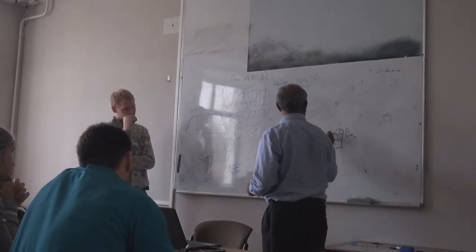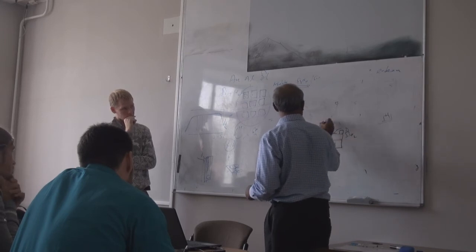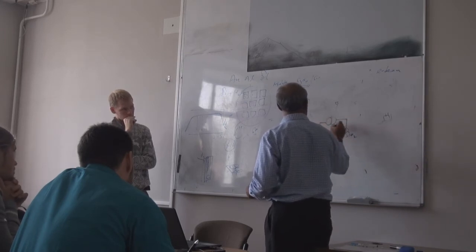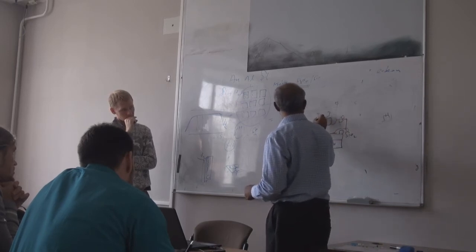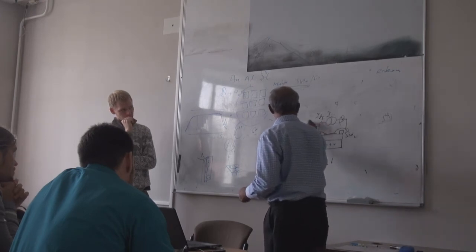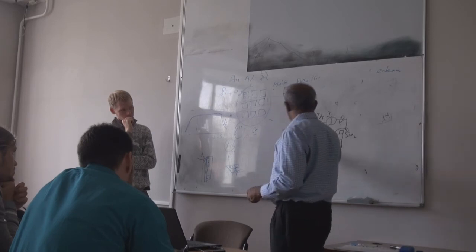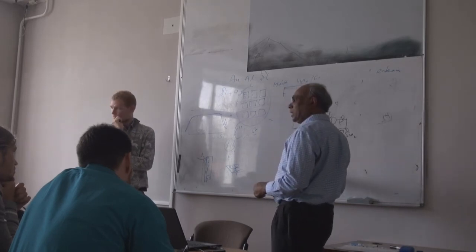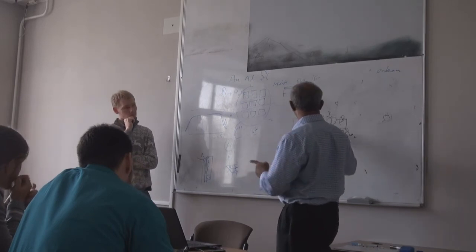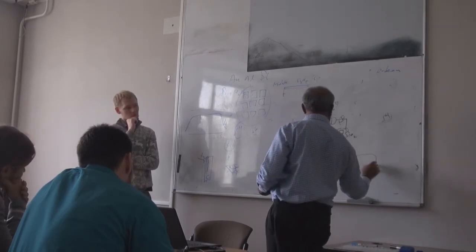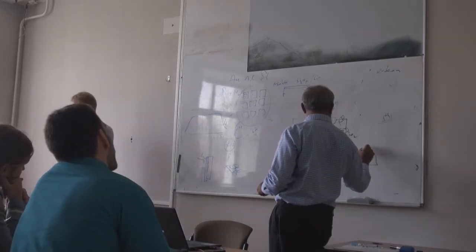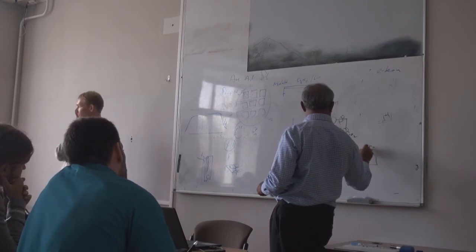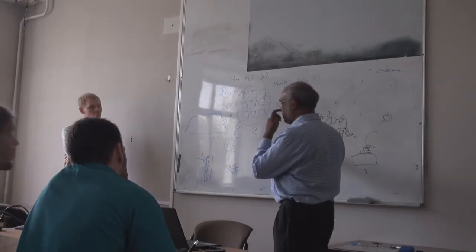First we apply current and voltage here. This is what we call the source-drain current. Then we apply another voltage. This is the gate voltage, what we call the bottom gate. If you want, you can put a top gate. If you have a nanotube here, you can put some silicon dioxide and put a gold. Then you have the top gate. But this is much easier.